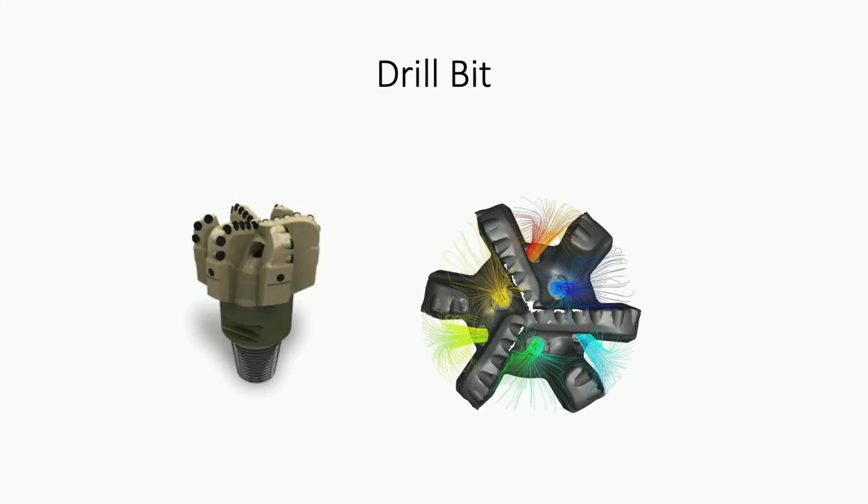So here's a picture of our bits. The black knobs that you see on the top of this bit are made out of diamond. So most of them are diamond or carbide material, so they're very expensive. A bit like that will probably go for about $30,000 or more. The cool little things coming out of the bottom of the bit, we call them jets, and the fluid actually comes out to help lubricate the bit itself, and to push the mud and the cuttings away from the bottom of the bit and back up the wellbore.